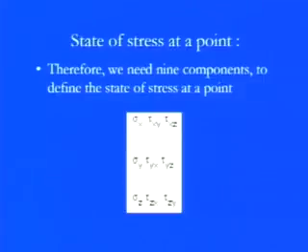So stress is known as a tensor. That means it is neither a scalar quantity nor a vector quantity, it is a tensor quantity. To describe the stress at a point, we need at least a 3 by 3 matrix, or a total of 9 elements, with which we can say how the stresses are set up within the object, or how they behave if a load is applied on an object. So now it is a general phenomenon of stress.